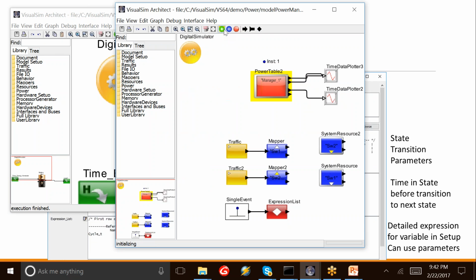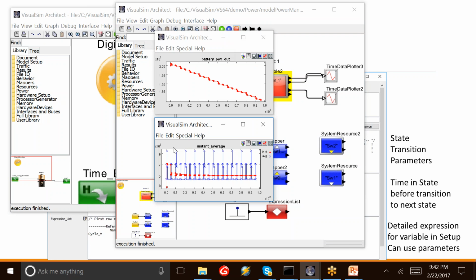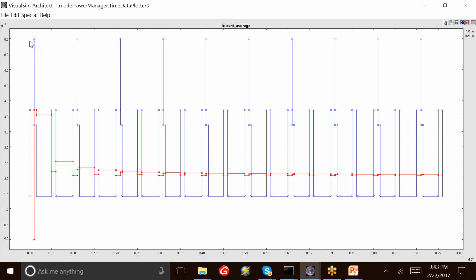What you see is the power output, and this is the instantaneous and the average power. One of the things we talked about earlier on is that you have these spikes. Most of the power is at this level. You have these spikes. So what happens? Your enclosure, your heat dissipation, everything has to be designed to this level. If you can do some shifts, you can drop that right down here.